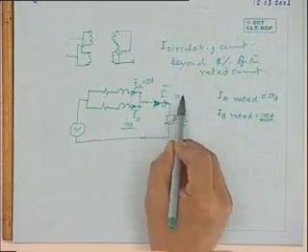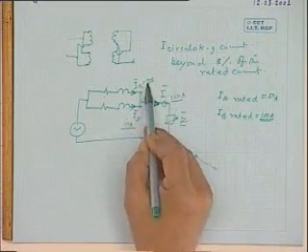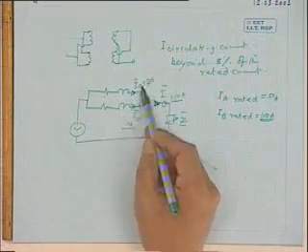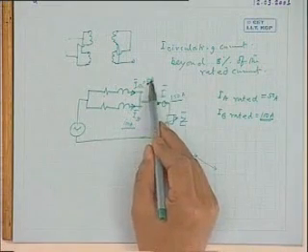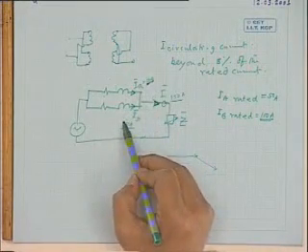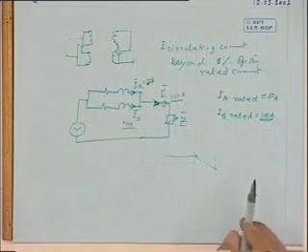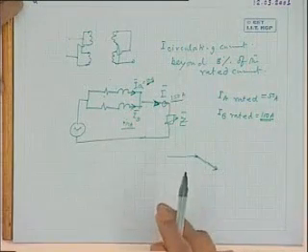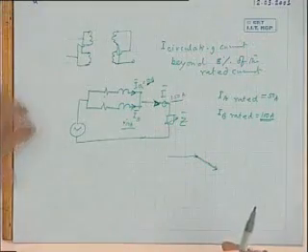That is, if you want to take 150 ampere here, then this current ratio will be 1:2, like that. But the magnitude of the current here will be greater than 50 ampere, and this will be also greater than 100 ampere. So total kVA output will be slightly less than the kVA handled by each of the transformers.